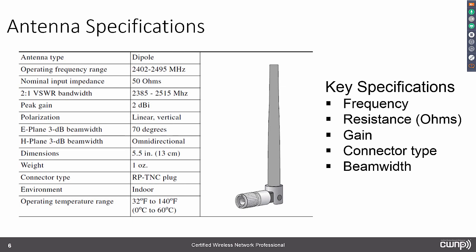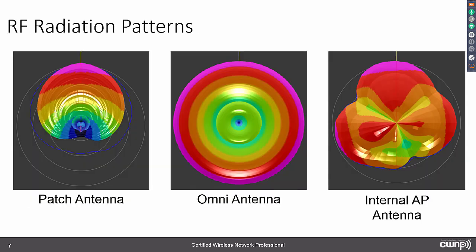So these antenna specifications can start to help you understand it, but there are visualization tools that help us as well. Let's take a look at a visualization tool that's available in a software program from IBWave called IBWave Wi-Fi, and it is a site survey, a virtual planning tool that helps you to plan or design a network based on algorithmic propagation patterns of RF signals in a space.